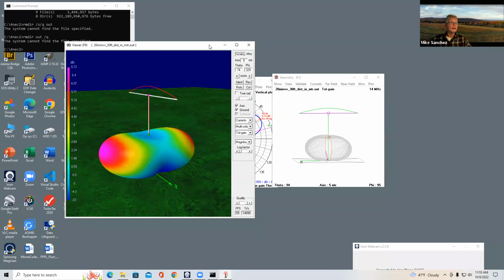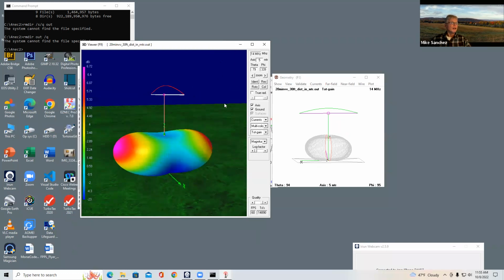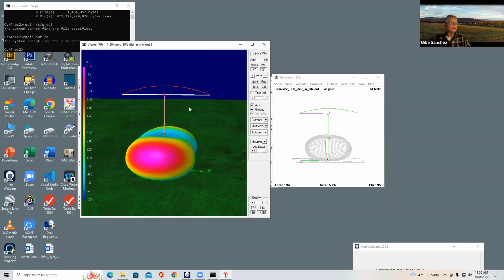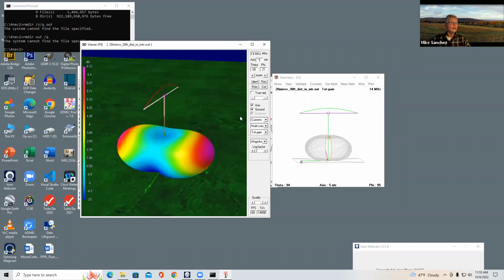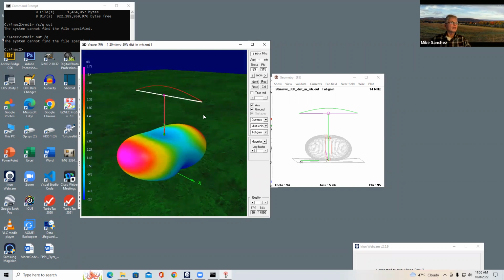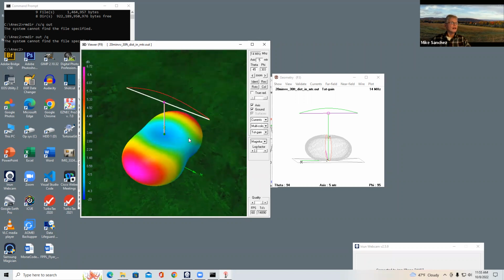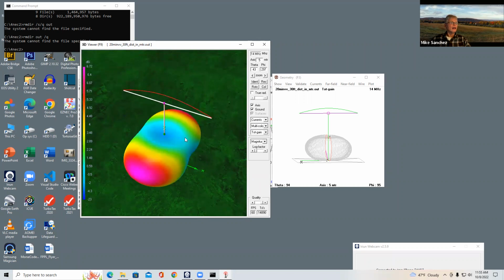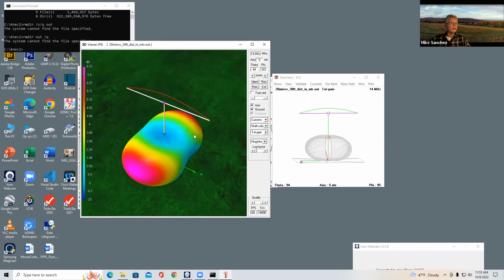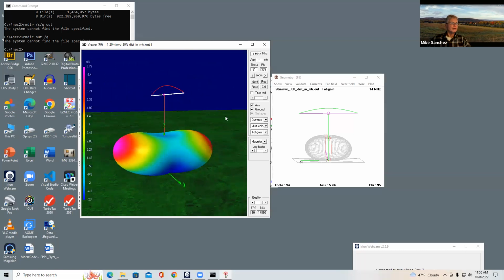And I will show that if we have time in this class. But this, for complicated radiation patterns, is a good way to get it in your mind. You can even take Google Earth and cut this out, and lay the pattern down on Google Earth, and then follow the lines from the pattern to what countries, and really teach yourself how your antenna is going to work in the States, which states you're going to get.